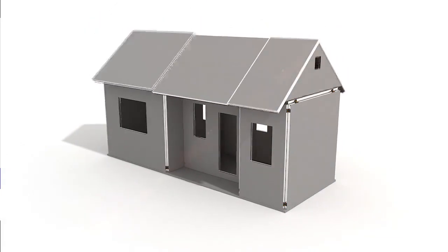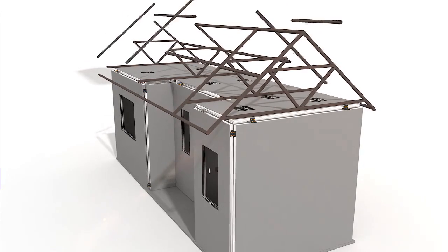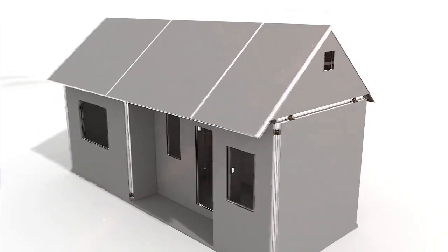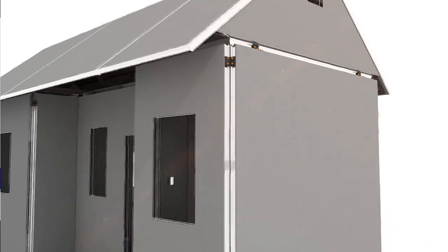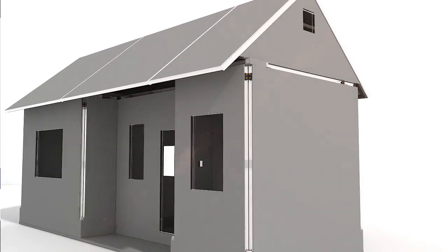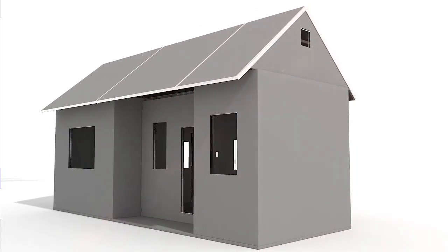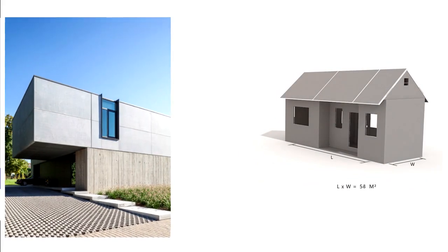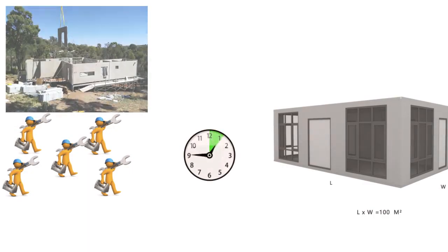The roof can be installed section by section or as a blanket with truss on the roof beam. Strengthening welding will be done between plates after the whole structure is completed. The thermal bridge process of the joint should be strictly done according to the construction drawings. A building within 100 square meters is usually completed within 5 hours by 5 workers.